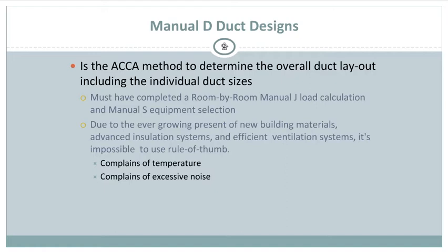So now you have to do these calculations in order to make sure that these furnaces are working properly, they're getting the right airflow, the right pressure in these ducts, and it keeps the house at the right pressure. Since we're building these houses energy efficient and building them real tight, pretty much anything below 70 HERS rating, 70, 65, 50, I've seen them as low as 42, almost close to net zero units. So be very careful on what kind of equipment you're installing and so on.